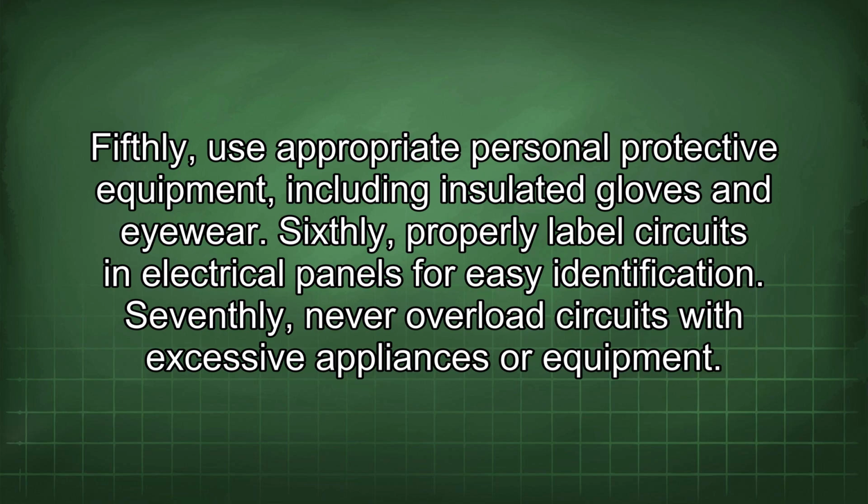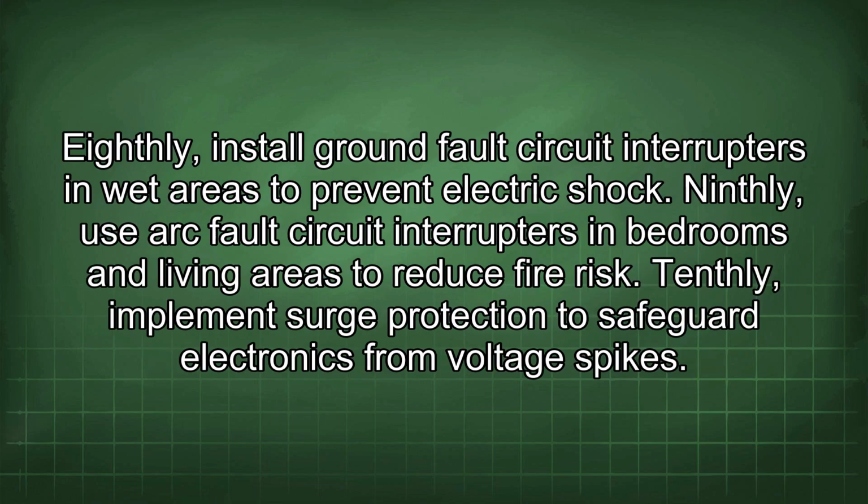Seventhly, never overload circuits with excessive appliances or equipment. Eighthly, install ground fault circuit interrupters in wet areas to prevent electric shock. Ninthly, use arc fault circuit interrupters in bedrooms and living areas to reduce fire risk. Tenthly, implement surge protection to safeguard electronics from voltage spikes.